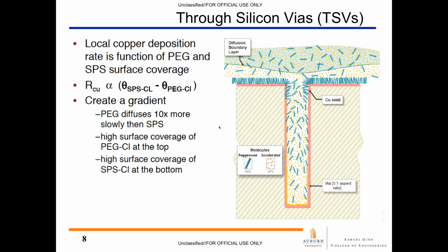And that is a time-consuming process, and so you typically, for many reasons, want to leave a very, very thin layer of copper on the surface, but you have to completely fill this hole. And the copper plating manufacturers have come up with a technique which uses different additives.